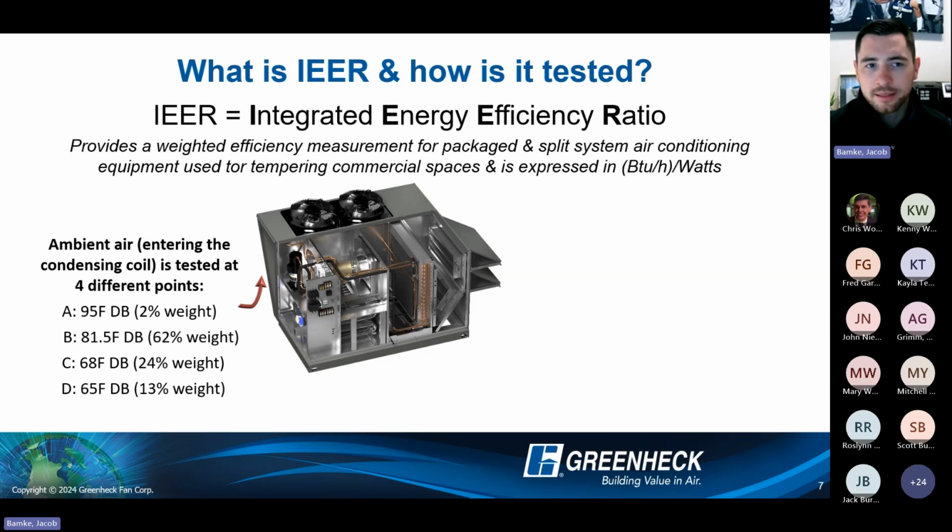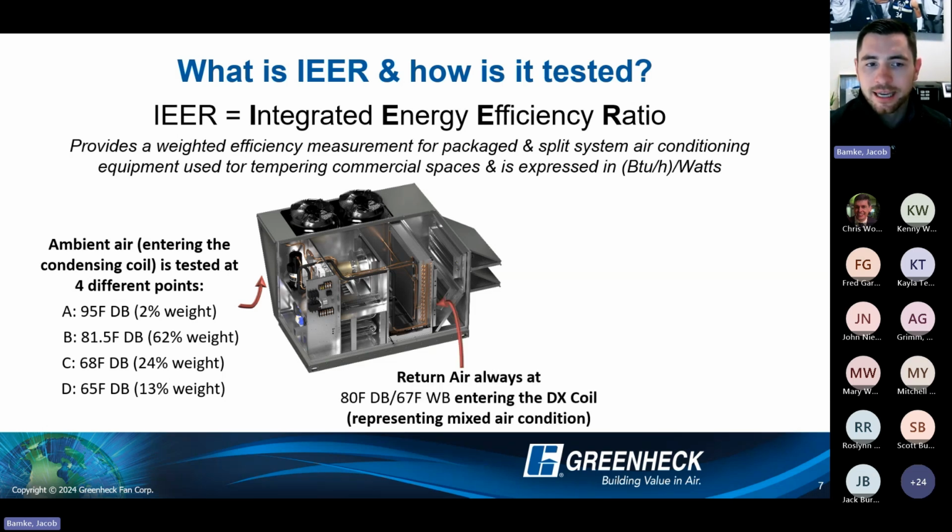What you look at with this IEER test is in each one of these points, the return air never changes. So what's entering our indoor coil is always going to be 80-degree dry bulb, 67-degree wet bulb. So it represents a true recirc type application, or if we think about those VAV type applications. The other thing to point out is IEER is weighted to 98% part load conditions.